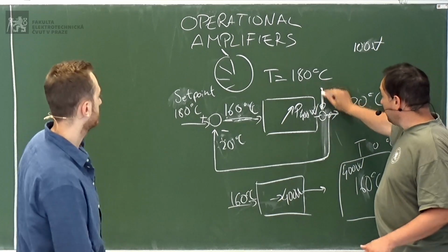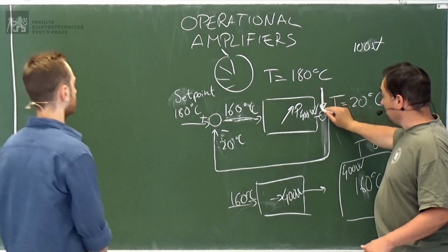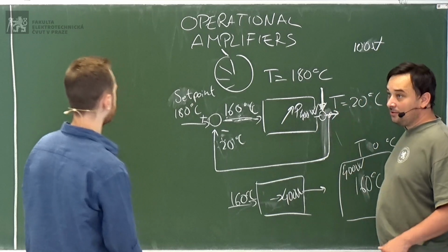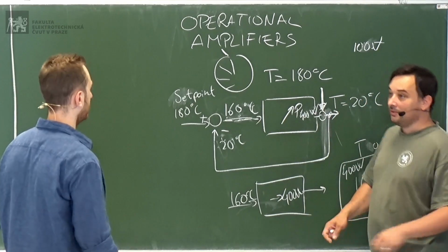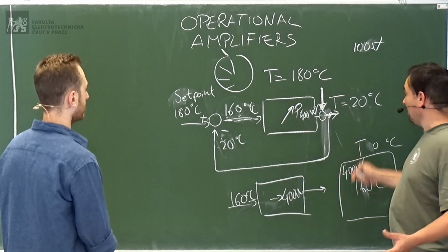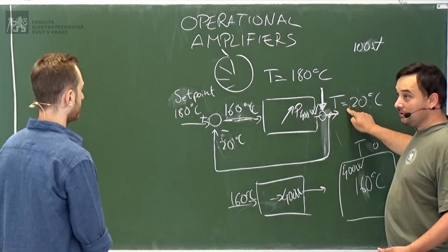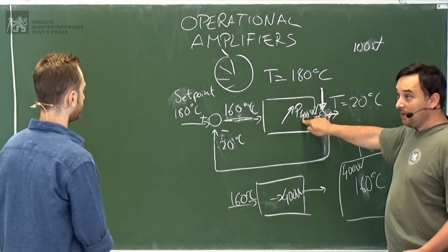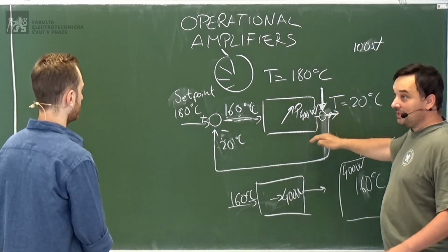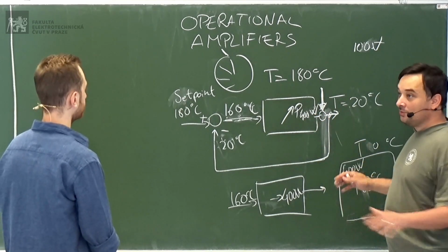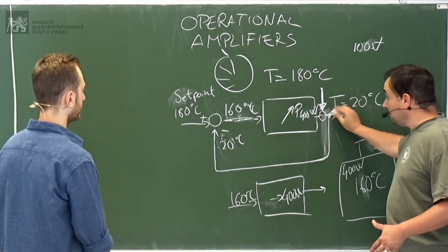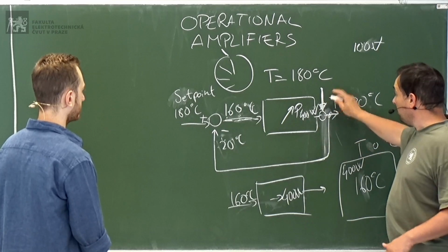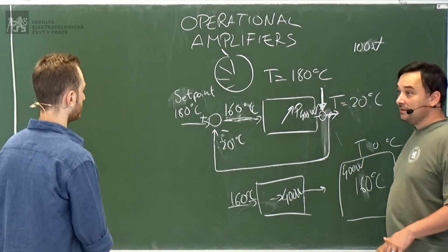If you put here some external cause which changes the temperature of the oven, like you open the oven or the environment changes, then this temperature will change. And if you give still the same power, because you set 400 watts constant, then you would have a different temperature. But if you have feedback, you say, okay, look, now here I have a disturbance.